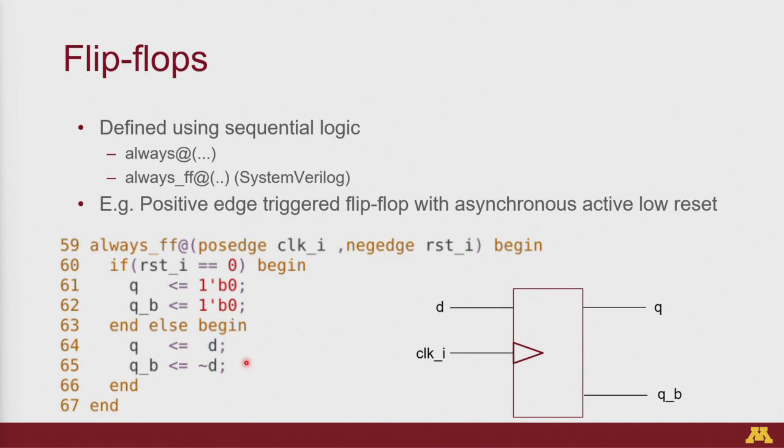No, if you declare it as a combinational block, generally you wouldn't want to put a non-blocking in a combinational, and I'm not sure, but I think it may give you an error nowadays. That's one of the intentions, that you should not have flip-flop logic within combinational. Similarly, you should not have combinational logic within flip-flop. They're meant for two different purposes. Whenever we think of non-blocking, we always think of the flip-flop operation. So this would generally mean that these two are working in parallel.